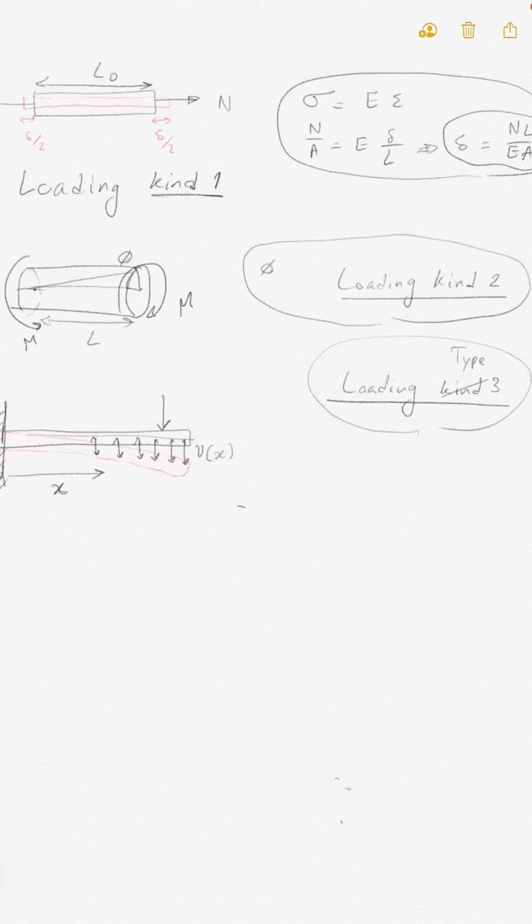Example: let's say you have a beam that is simply fixed to the wall and you have a load of 2K. Somebody asks you to find the reaction in the wall. For example, you want to design a fixture here, a bolt or something that you can fix to the wall. If I draw an FBD, you have Fy, force in the y direction, a moment here in the wall, and then you have the 2K here.